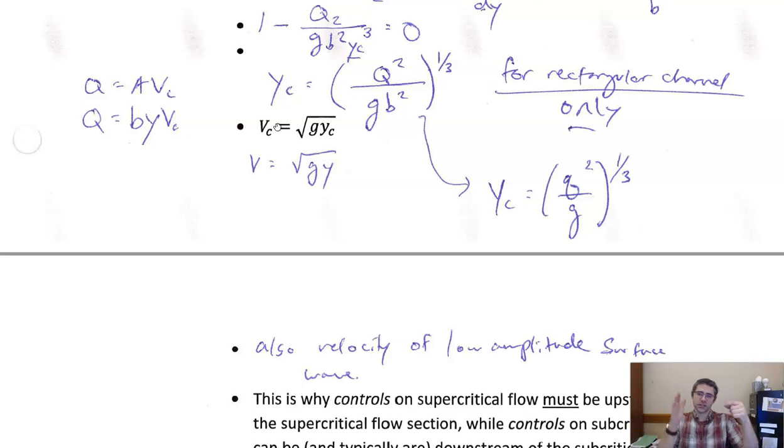So that's the transition point where if it's moving slow and I drop a pebble, again, some ripples can go up and some can go down, even though the ones going up are going to go slower. As the velocity gets higher and higher, at some point, all the ripples go downstream. And that's at that critical depth, critical velocity.